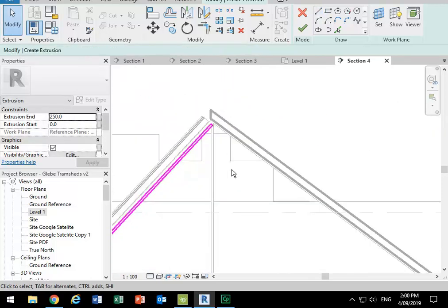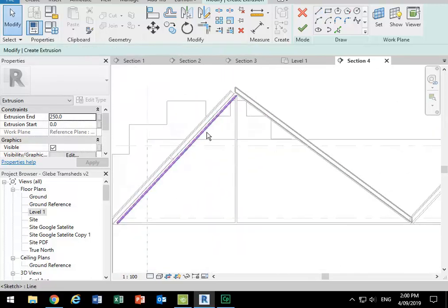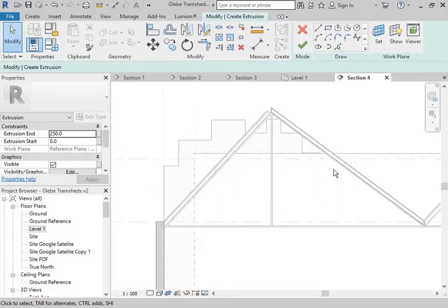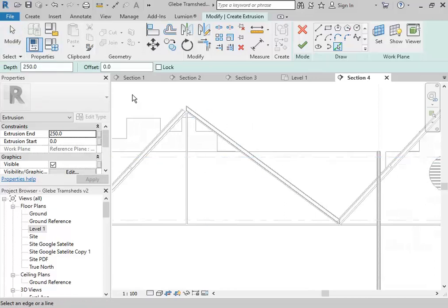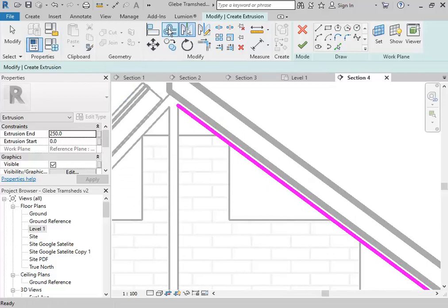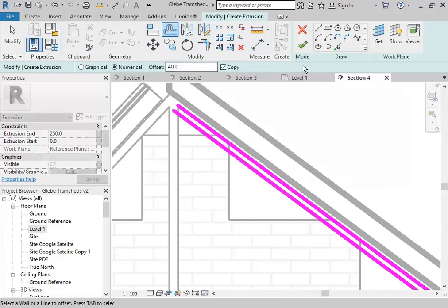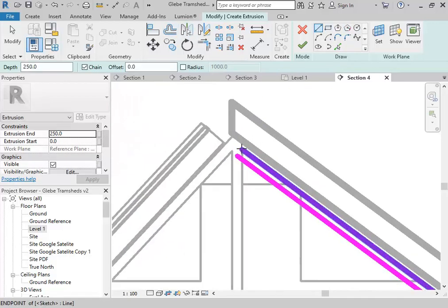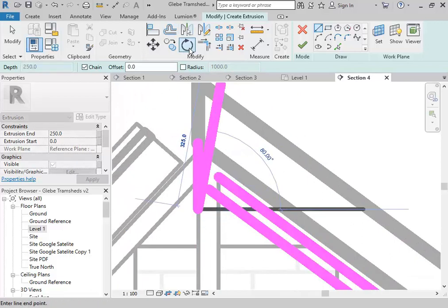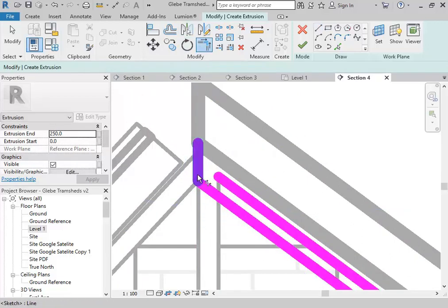And maybe if that's the solid, actually that's the glazing. I'm doing it the wrong way, aren't I? It should be on this one. Yeah. Okay, I'll start again. So, picking this one. Then offset, yep, 40. Draw the line, so maybe to make it neat, I'll come down from here, straight line, and then use trim to join those things together.